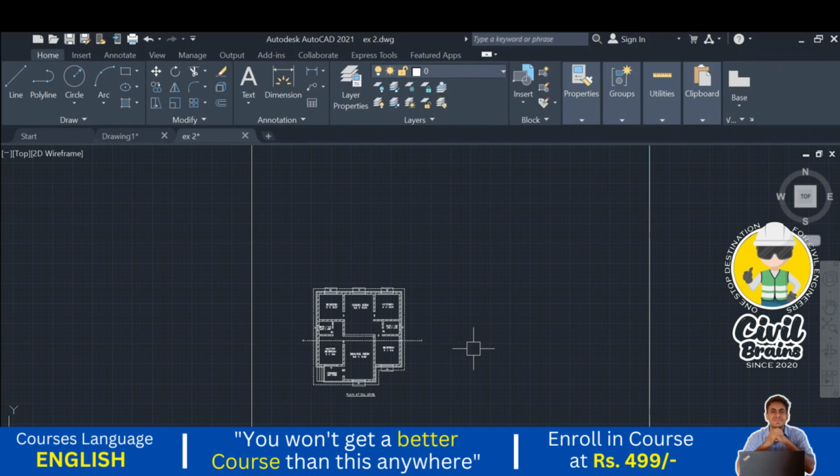So in the last video we completed the building plan. Here you can see this one, using the line command, the offset command, the edit commands and other tool commands. This is our basic presentation drawing which we need to minimally give to the site. It includes the walls, the doors and windows, the projections, that is plinth projections, slab projections and chajja projections, and all the details of the room sizes. And the hatches also we need to show.